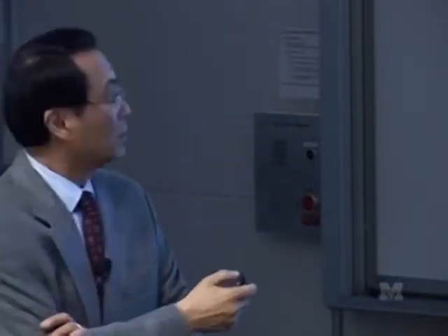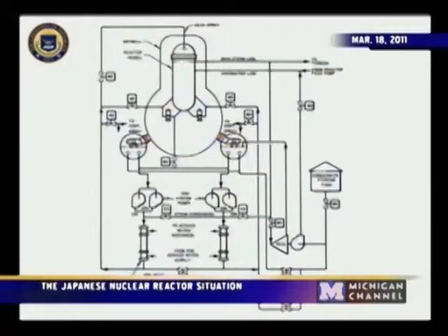And of course, the uncovering of the reactor and the core continues on and off. And that's when the Tokyo Electric Power crew started pumping seawater through fire engine, fire hoses, and so on into the reactor vessel. And this mode of emergency cooling was considered and included as a way of handling emergency situation like this. So it was not something that they came up with in the last minute, but was in the technical specs and operating procedures for the plant. So effort was made, and effort is still continuing to keep the damaged reactor core under cover and cooled, the way I understand. So again, the hydrogen escapes through the relief valve that was manually opened.